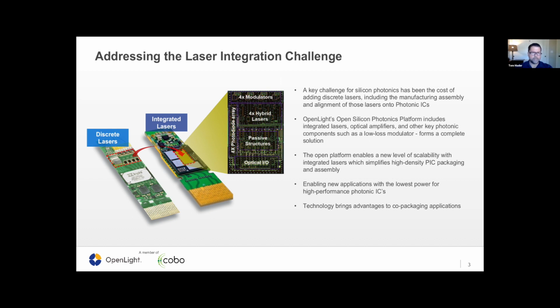And we end up focusing a lot on the laser. The laser is very important, and it allows scale. But over time, we knew, and are having confirmed through our customer interactions, that optical amplifiers are also very important, in particular for some of the arenas such as LiDAR and sensing. You can re-amplify across your chip, and it's for the more complex chips in a lot of the areas. The optical amplifier is actually a key differentiator, particularly with the low loss in and out of the amplifier. We have only a few tenths of a dB loss from the amplifier or the laser.